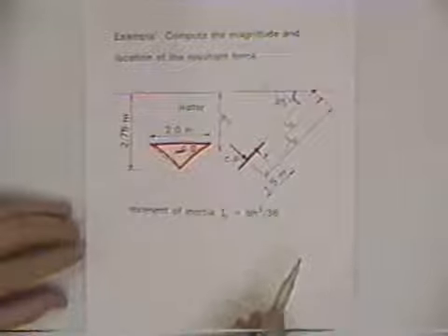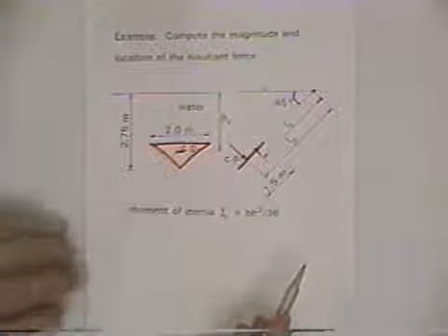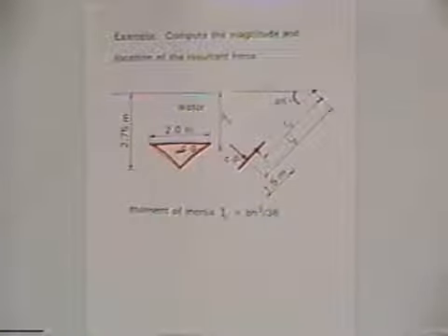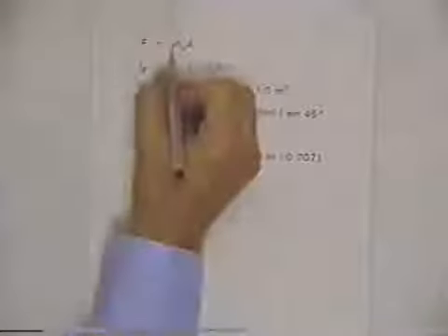And in your Fundamentals of Engineering reference handbook, it gives formulas. There's a table that gives formulas for moments of inertia, so we can get the formula for triangular shape, and using that information go through the computations. And so let's do the computation. Now, basic equation. Force is pressure times A, and pressure is the unit weight times the head measured from the surface. That's a vertical measurement from the water surface to the center of area of the plate upon which the force is being exerted by the water.